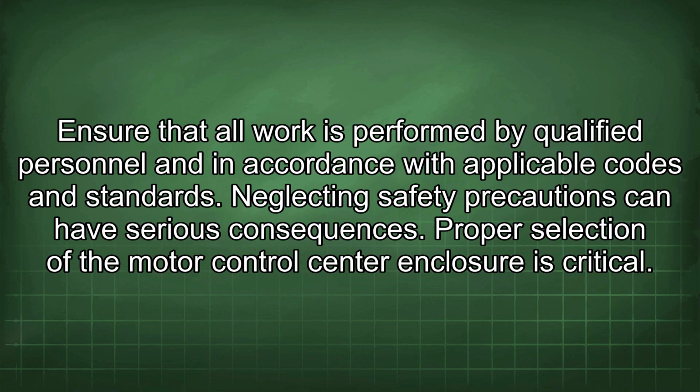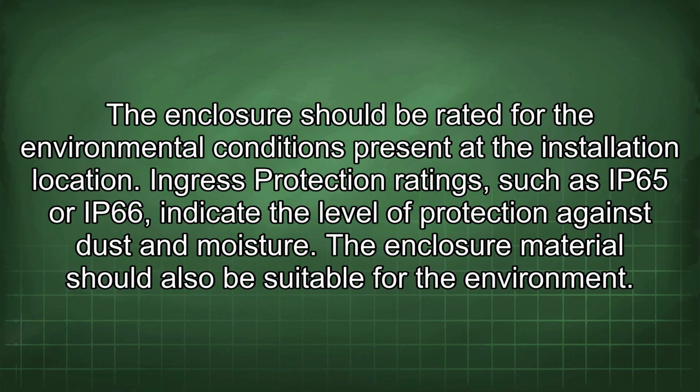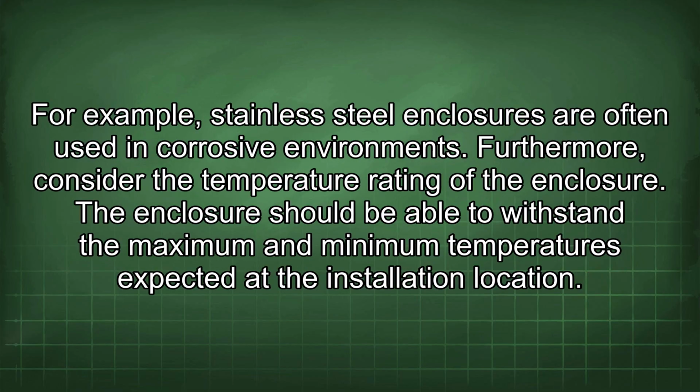Proper selection of the motor control center enclosure is critical. The enclosure should be rated for the environmental conditions present at the installation location. Ingress protection ratings such as IP65 or IP66 indicate the level of protection against dust and moisture. The enclosure material should also be suitable for the environment. For example, stainless steel enclosures are often used in corrosive environments.